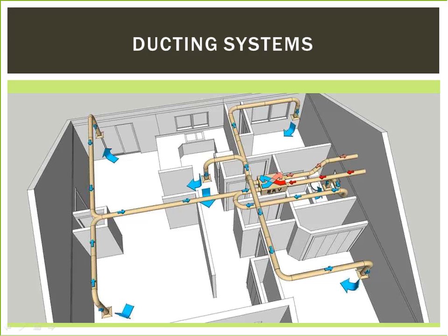Traditionally, air ductwork is made of sheet metal, which is installed first and then lagged with insulation as a secondary operation. Ductwork manufactured from rigid insulation panels does not need any further insulation. It is installed in a single fix. Light weight and installation speed are among the features of pre-insulated aluminum ductwork. Also, custom or special shapes of ducts can be easily fabricated in the shop or on site.